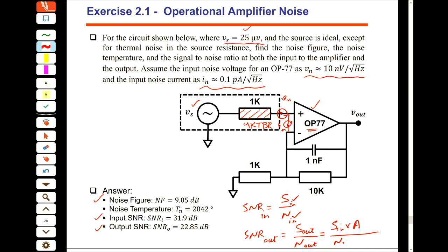is the noise that we get from our source, which is N in, again multiplied by gain, plus the input referred noise of the amplifier, multiplied by gain. I put here gain 1, gain 2, because the gains are different. We will see that. Up to here you agree with me or not? Okay? And then it says, what's the noise figure?